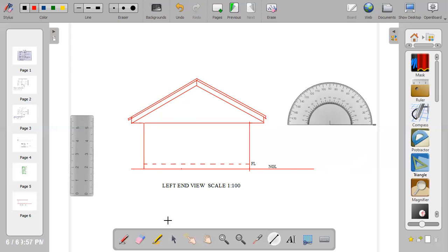When you are done with this, bring out the ridge cap. The ridge cap is also 0.1. It's placed on the roofing sheet to prevent the penetration of water from the top. So once you are done with this, erase this part. We're almost done with our front elevation.